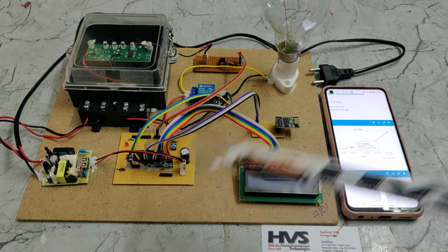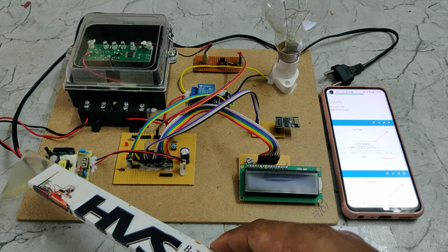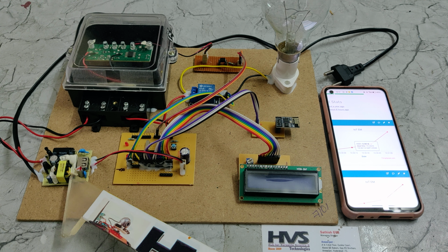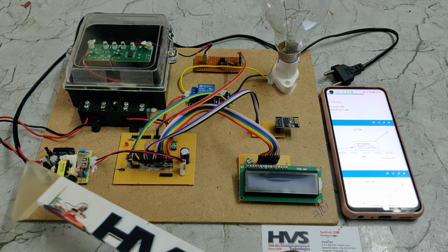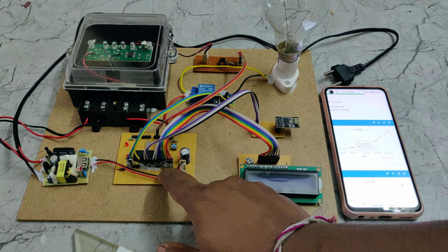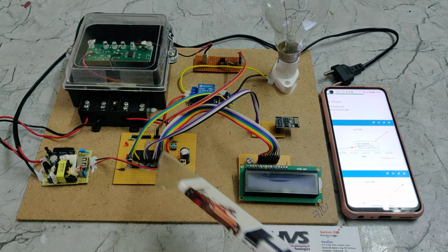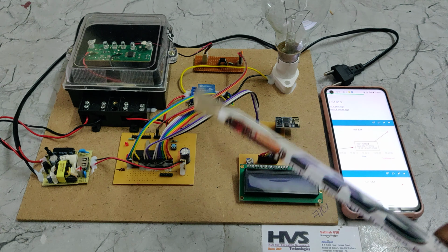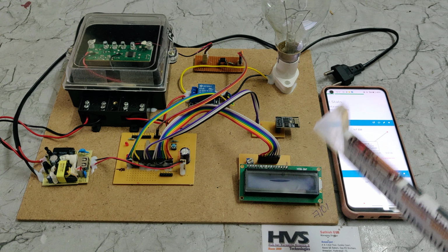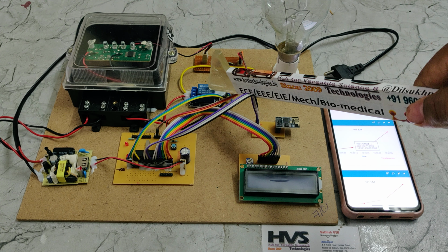So the whole system gets power supply from this 230 volts AC input, which is distributed in parallel to the energy meter as an input, and also to this regulated power supply board, which takes the 230 volts AC input and provides us the 5 volts DC output to these wires, and that is the main operating voltage for our microcontroller. So it will start reading input from the input module, and once it crosses 0.004 kilowatt hour, then the system will cut off the power to the load by using this electromagnetic relay.